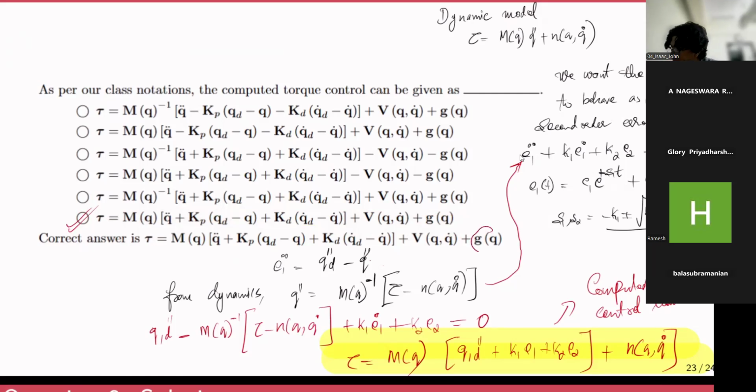There is also one more term, right? G(q). Here, I have considered the model without G(q) because I didn't choose to model that. But maybe you can also have a gravity term here as well. And if you have other effects in your own robotic system, like damping due to viscous friction or Coulomb friction, maybe some effects due to backlash, all these things can also be modeled, if you can model them, and they would also get reflected in the control law.